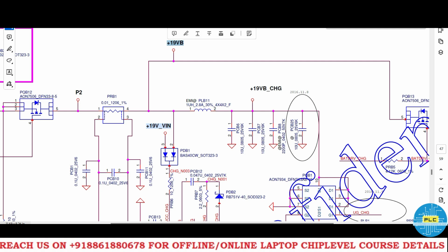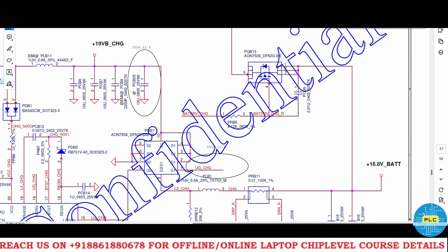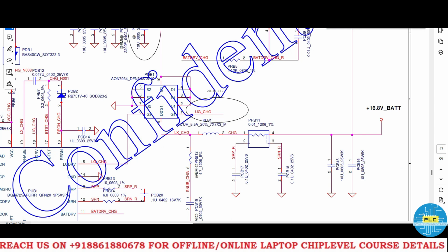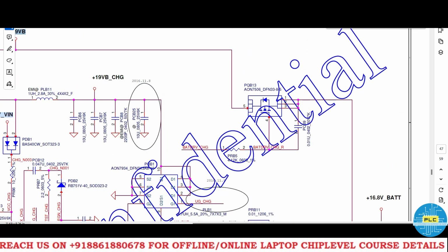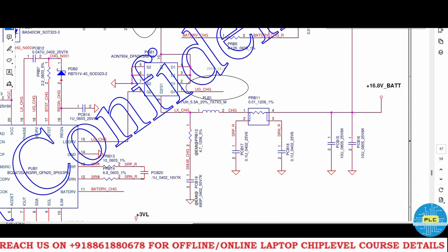Okay, here it is connected to the MOSFET. Which MOSFET? The discharging MOSFET. This one is connected to the battery section. The battery section has the ground capacitor. See, here this capacitor may have the issue. Okay, here one CLR is there. Here also these capacitors are connected to the ground. Maybe here or maybe here is the issue. In case of an issue here, you won't get the gate voltage properly; you will get 19 volts or battery voltage. Okay, these are the main suspect points.